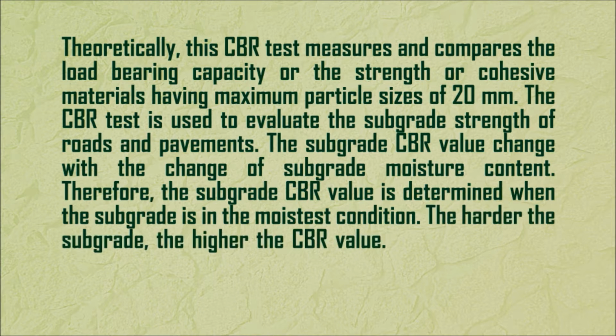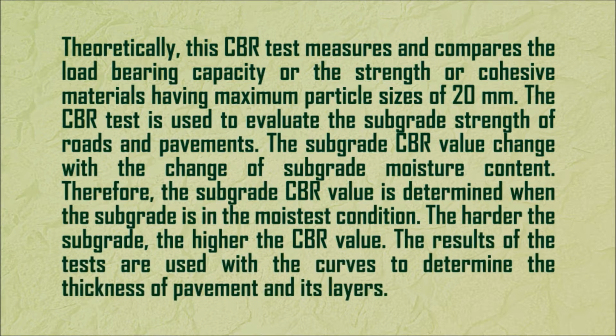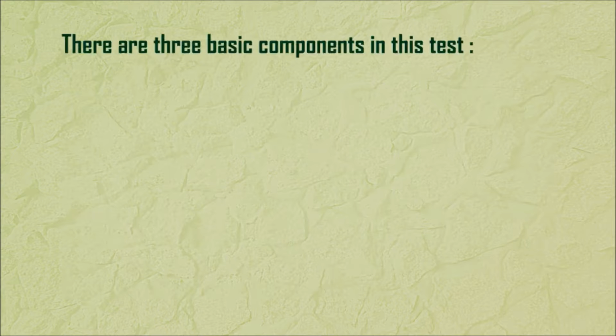The harder the subgrade, the higher the CBR value. The results of the tests are used with the curves to determine the thickness of pavement and its layers. There are three basic components in this test.